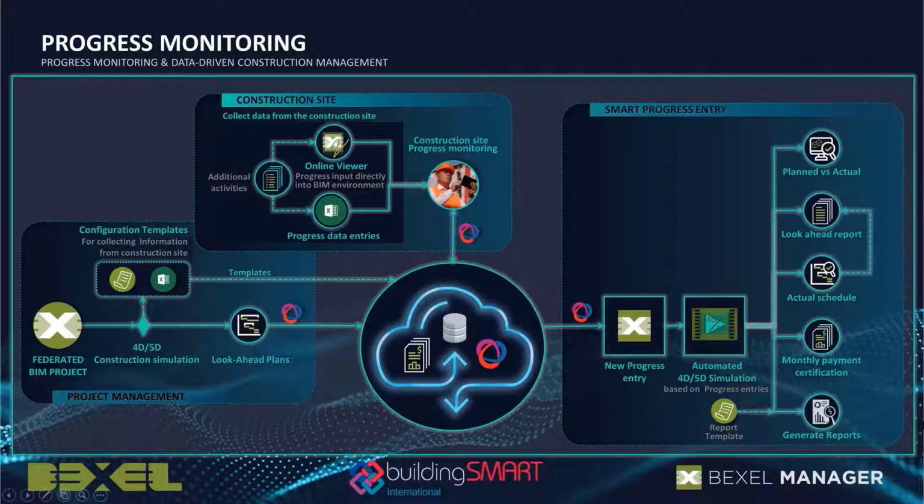After developing multiple what-if schedule analyses and optimizing the final schedule and accepting it as the baseline planned schedule, the user can start the progress monitoring process using this baseline planned schedule. Based on this baseline planned schedule, the user has the ability to manually or automatically create look-ahead plans for a specified period of time, which will include the elements that should be completed, all the quantities, resources, and price of the activities that should be executed in a certain period of time.